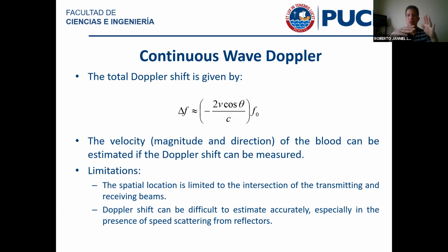So if you're transmitting something that has a certain amount of power at, let's say, 4, 5, 6 megahertz, by the time it propagates several centimeters and then comes back, it has lost a lot of energy from 6, some energy from 5, and a tiny bit of energy from 4. I'm exaggerating, but you get the point, right? So your spectrum doesn't have the same shape anymore. It's actually shifted towards the lower frequencies.